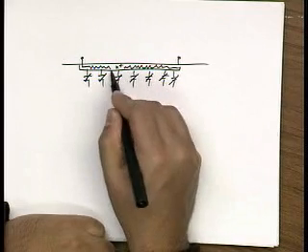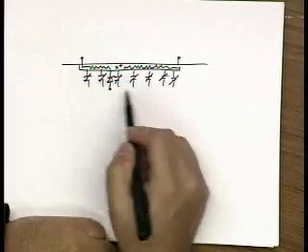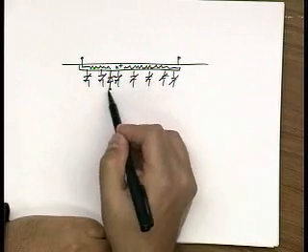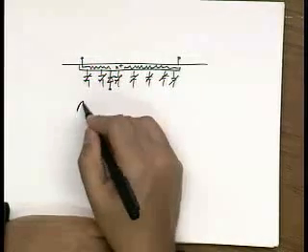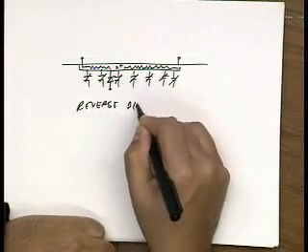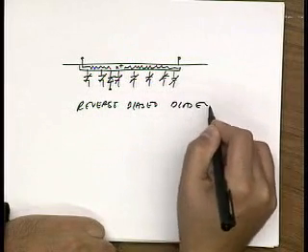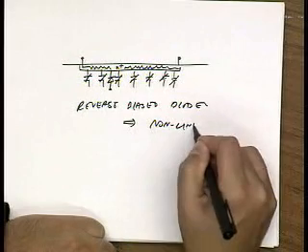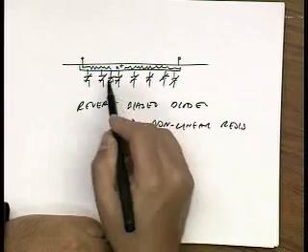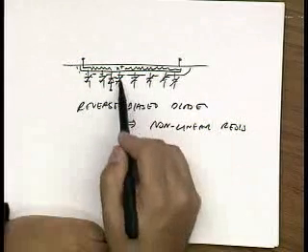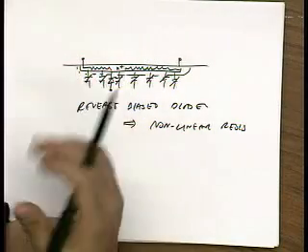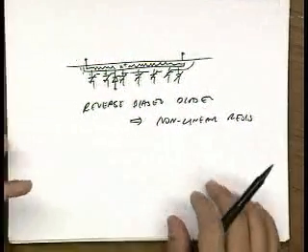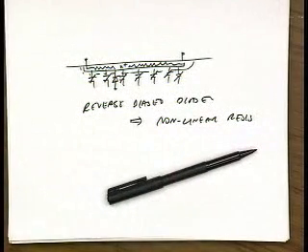So these are all reverse bias junctions. It's reverse bias to give you isolation from the substrate, but because this is a diode, it looks like a nonlinear resistor. Why is it nonlinear? Because the depletion region width changes as we change this reverse bias, which effectively changes the thickness of this diffusion region. That's bad. We're going to try to use these resistors in operational amplifiers that have really good linearity, and if our resistor has a voltage coefficient on it, that's going to hurt us.